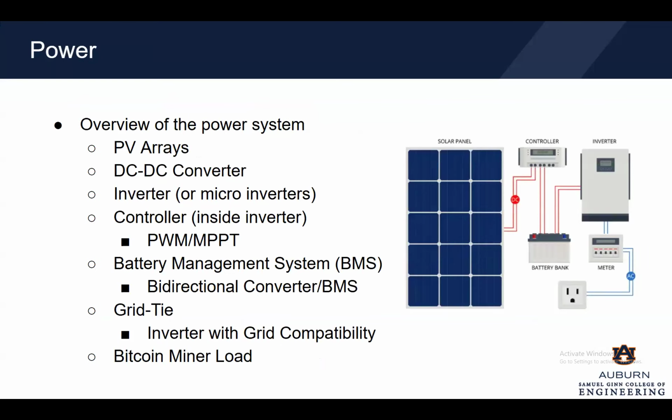Okay, so a little overview of our system here. We'll have our solar panels connected to a controller, which in this case is going to be inside of our inverter. We're going to have a battery bank, and then that is going to go to the load. In our specific case study, we did not connect to a meter or to the grid, but that is a possibility as well.